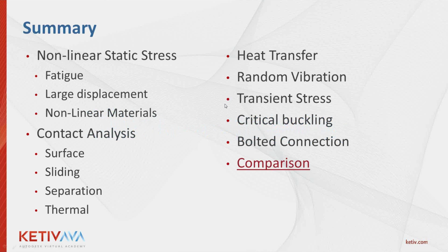But to wrap this up, thank you for those of you that stuck around for the bonus session. In summary, this Advanced FEA bonus one was to show you that you can take it a little bit further and still use it inside of AutoCAD in something called Nastran In-CAD, a separate add-on package that can do fatigue analysis, large displacement, nonlinear materials, as well as contact analysis, heat transfer, random vibration, some of the ones we mentioned, and even bolted connection, where it allows you to actually look at a study of a bolted connection.